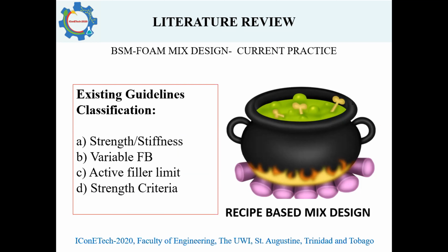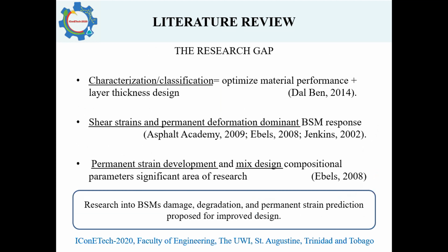In addition, a recipe-based mix design process is adopted with a variable foam bitumen binder content and an active filler content limited to a maximum recommended range of 1%. Indeed, the characterization and classification processes within these guidelines allow for an optimized material performance as well as an improved structural design process.